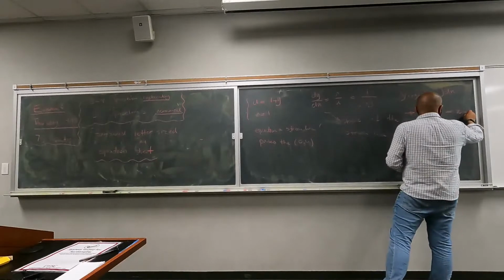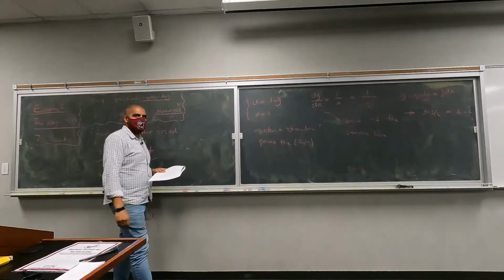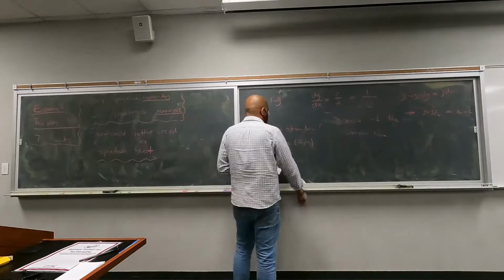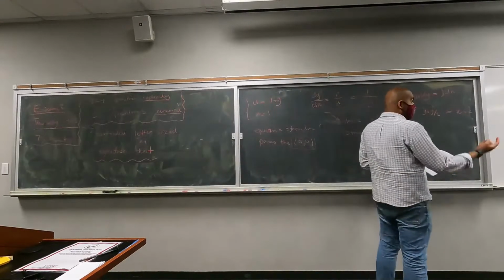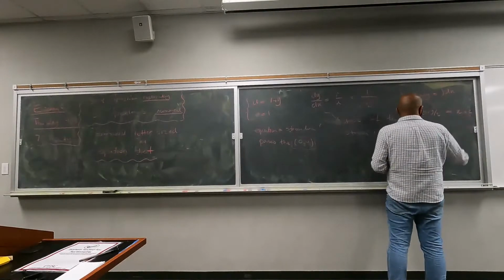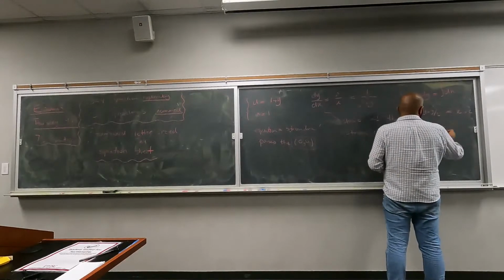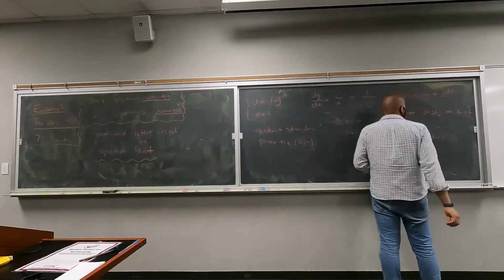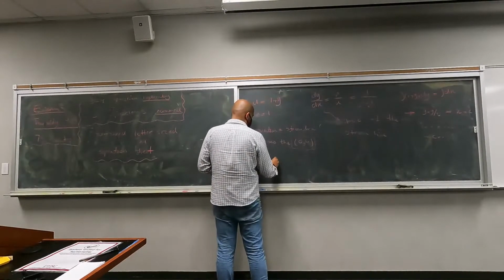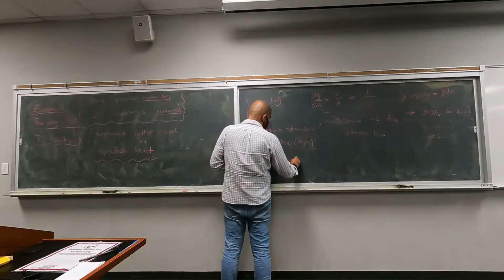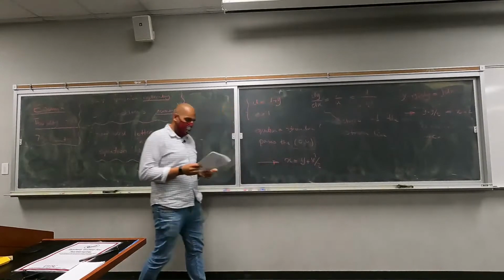Since on both sides we are taking an indefinite integral, we have to add a constant. But we are told that this equation passes through the origin, 0 and 0. So using those two points, we should be able to determine c. You plug in 0 for y and 0 for x, which means that c is going to be 0. So the equation of the streamline is x equals y plus y squared divided by 2.